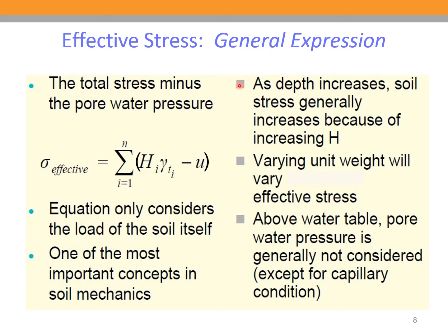As depth increases, soil stress generally increases because of increasing H. Varying unit weight will vary effective stress. Above the water table, pore water pressure is generally not considered except for capillary conditions.